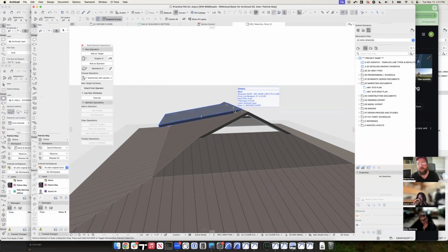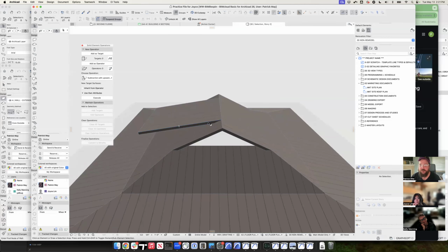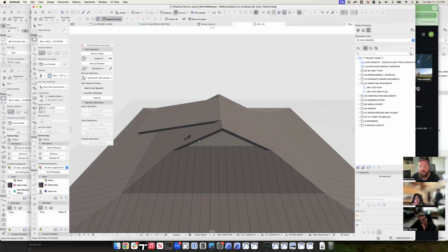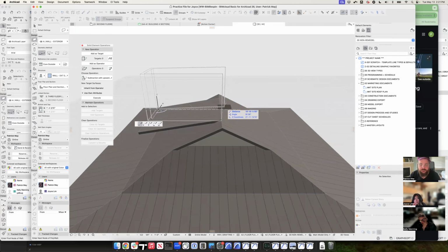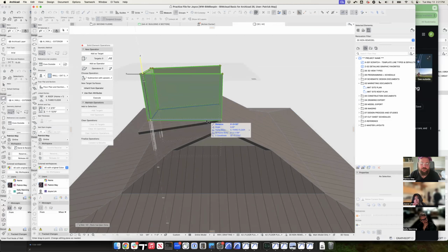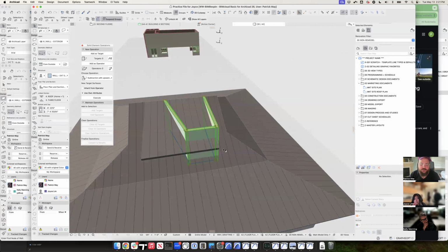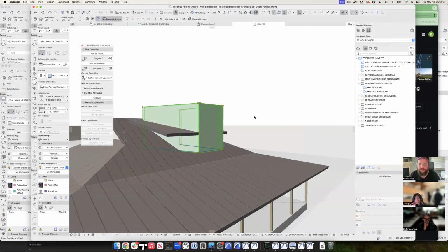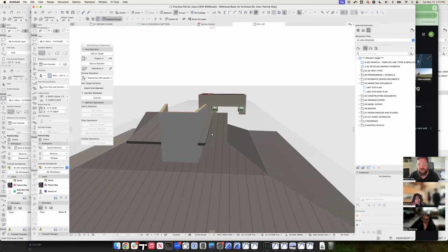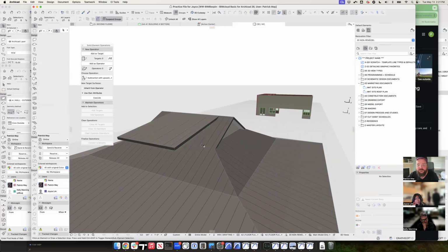And that's where, like when I was talking about the reference line on the walls and the reference point on the columns, if you sort of plan ahead on where those origins are at, making changes to the design later on is a lot quicker and easier and cleaner. For the walls that go around this, I would probably model that in floor plan, but really just sort of, I'll quickly rough something in here. Oh, that's way crooked. Anyway, it would be something like this, where I would have walls that came right here and trim those out. This is where like knowing which view to model in is really important so that you can be precise. But similar to what I did on the gable end walls, I would model these dormer walls as separate walls.